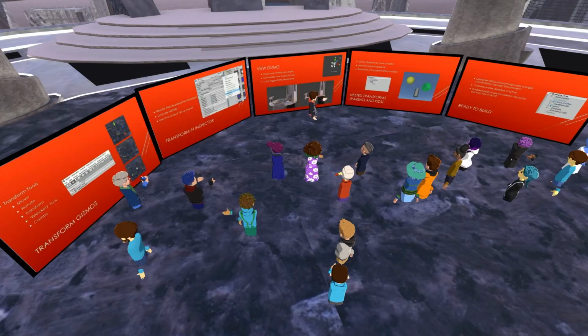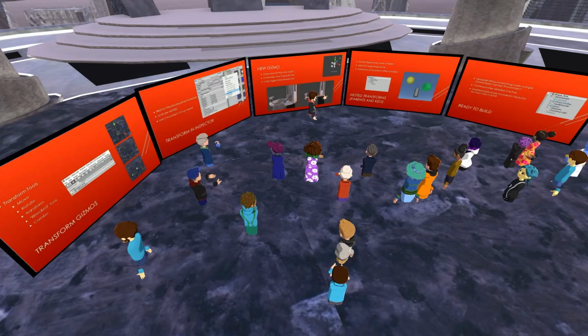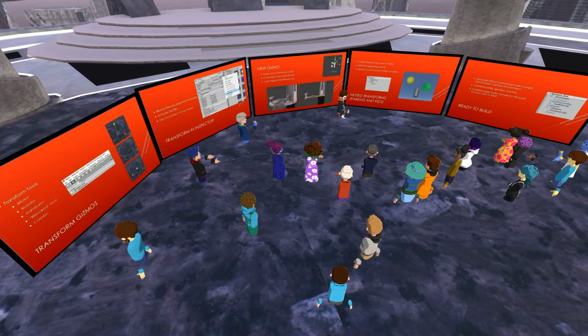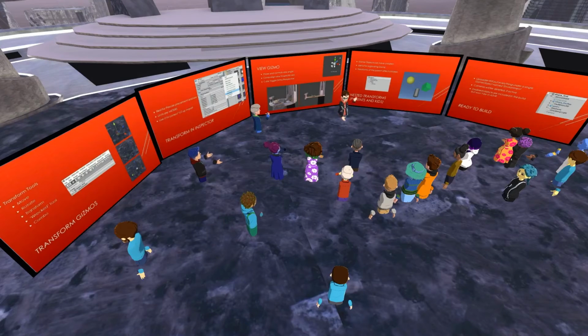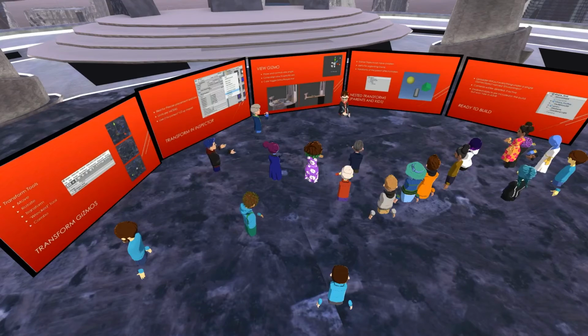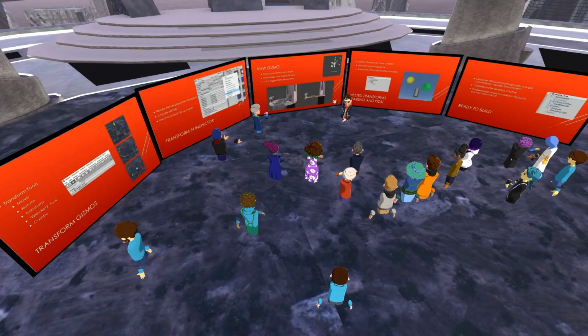So in this example, my sphere could be, say, at, I don't know, some arbitrary position. I can't randomly come up with 3 numbers right now. But my cube, if I look at the position of my cube, the position of my cube is not going to tell me its position in the real world. It's going to tell me its position relative to the sphere. As the sphere moves around, the position of the cube is not going to appear to change. Clearly it's changing because it's moving around through the world. But what Unity is probably going to tell me is its relative position to its parent.